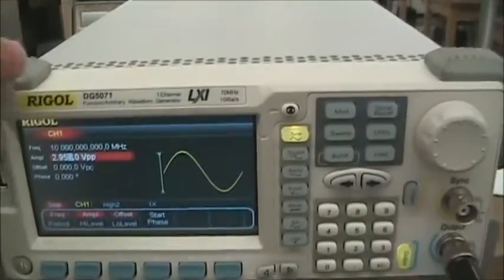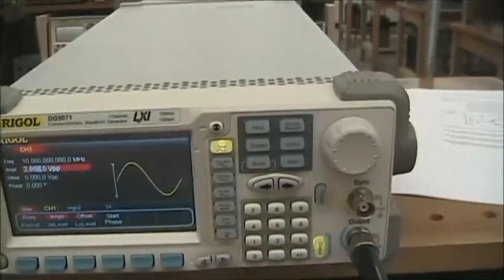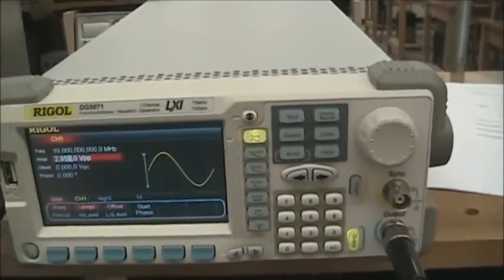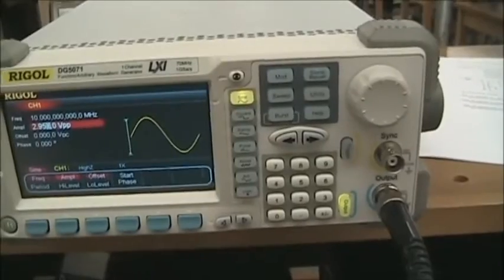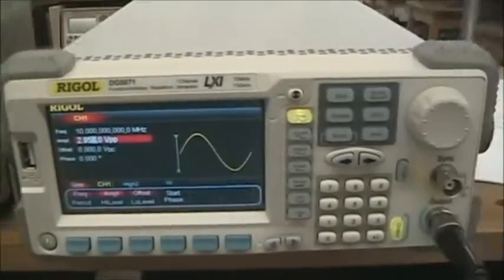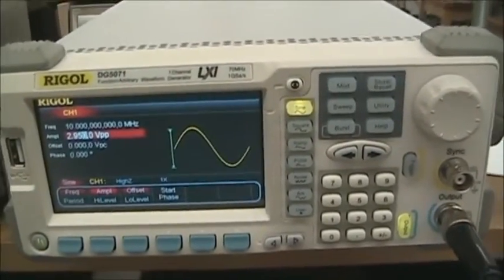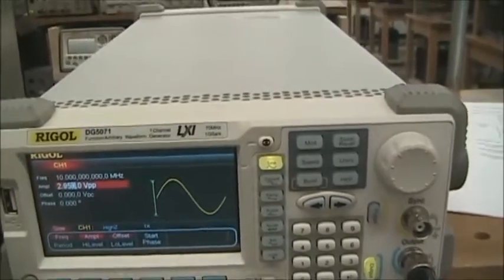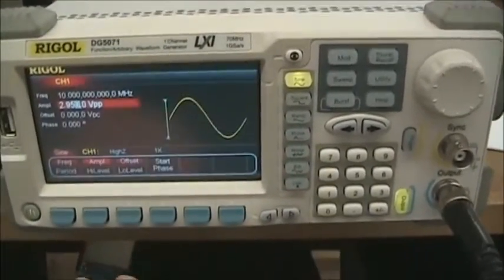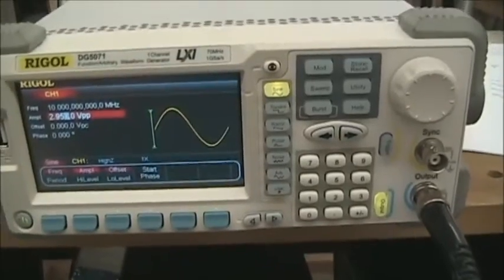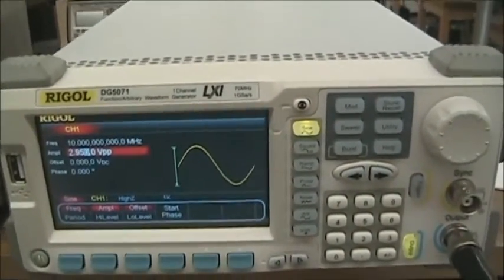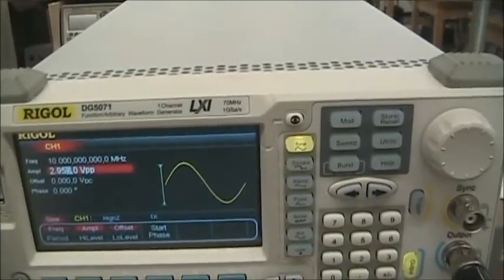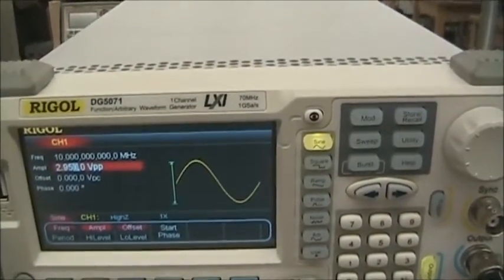Also, the generator can be set up for either assuming a 50 ohm output or a high impedance output. It gets confusing, so you must trust your measurements. So we trust the spectrum analyzer to read properly at plus 7 dBm. In the generator, there is a setting you could change to a 50 ohm load, and that would adjust the value. But for now, we're going to treat this as 2.95 volts peak to peak results in a plus 7